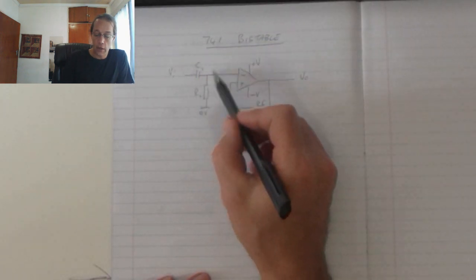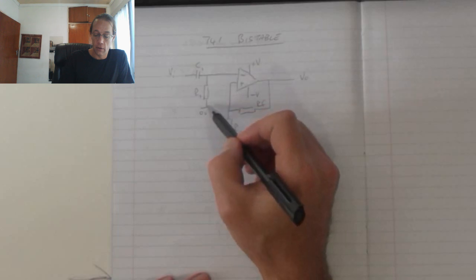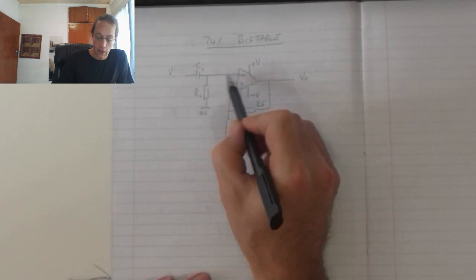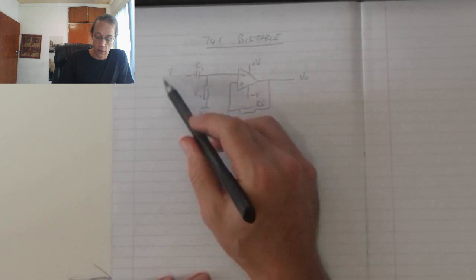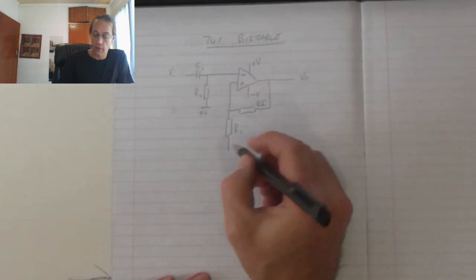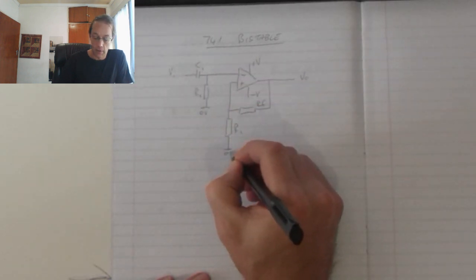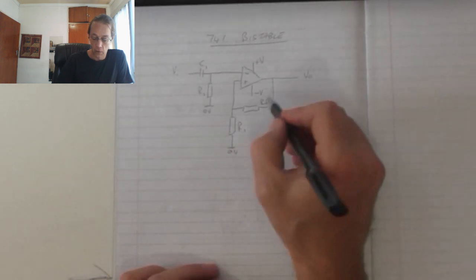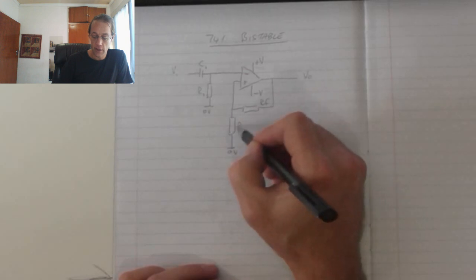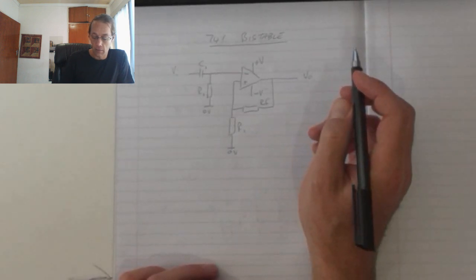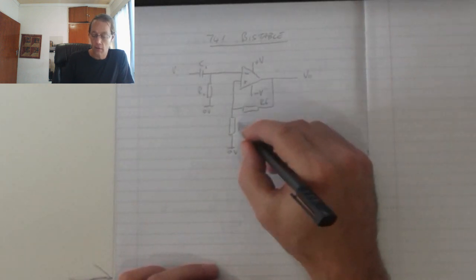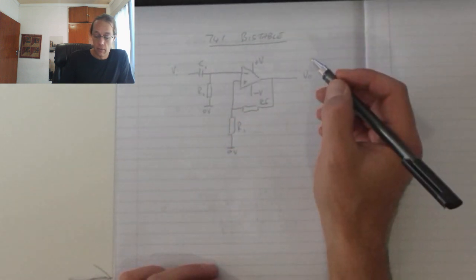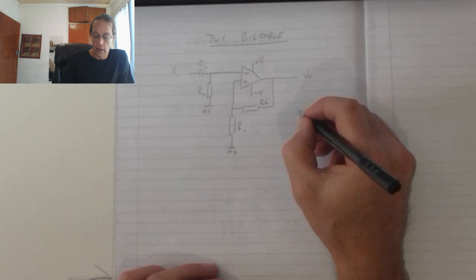At this moment we're not going to concentrate on this too much. We just have this configuration to ensure I've got 0 volts on the input when I do not have an input voltage connected. That point there also connects to my 0 volts. Now, the feedback resistor and resistor 1 will develop a voltage that is fed back onto my non-inverting input to serve as a reference voltage.